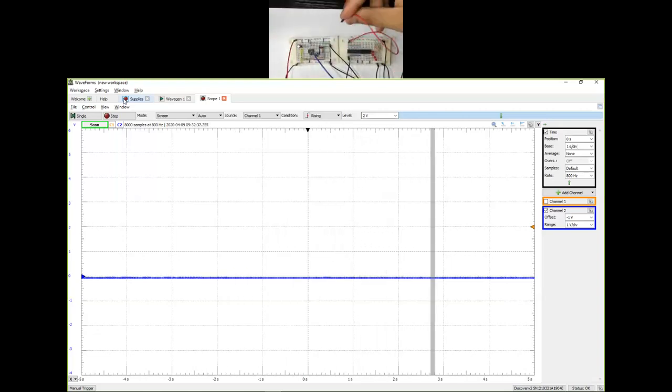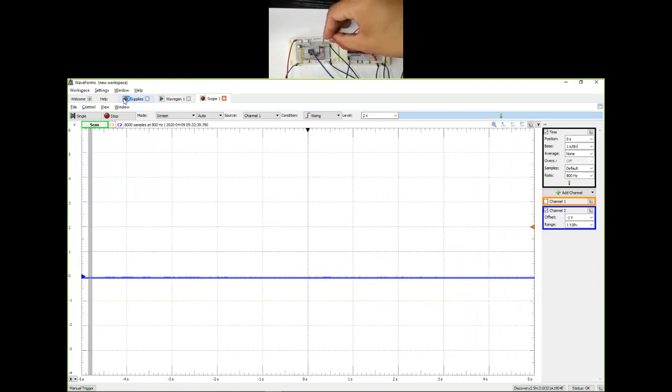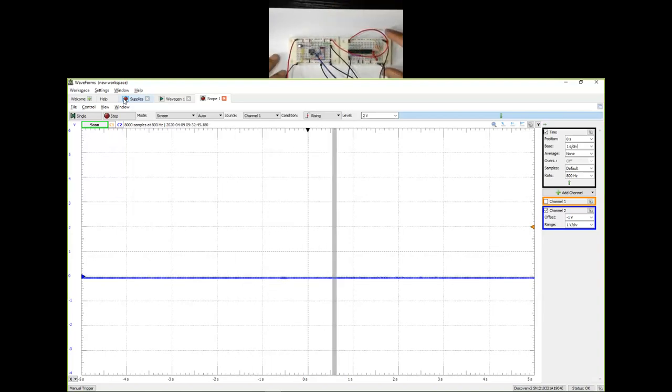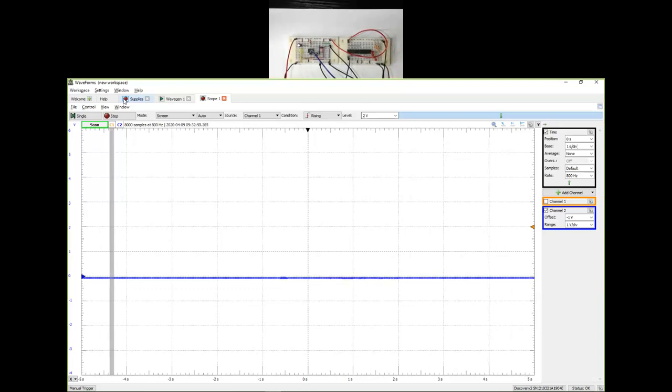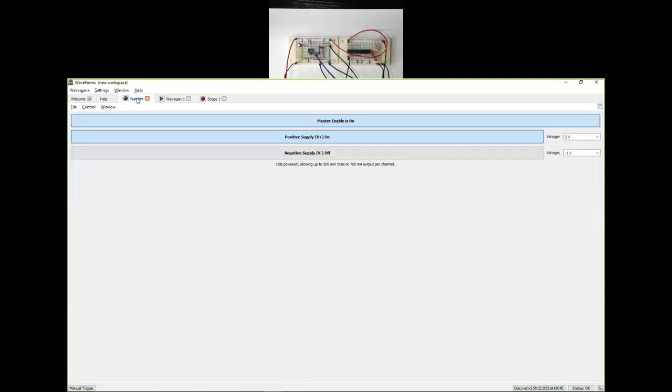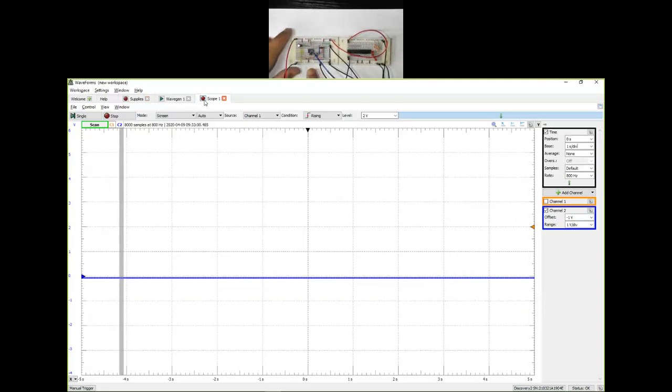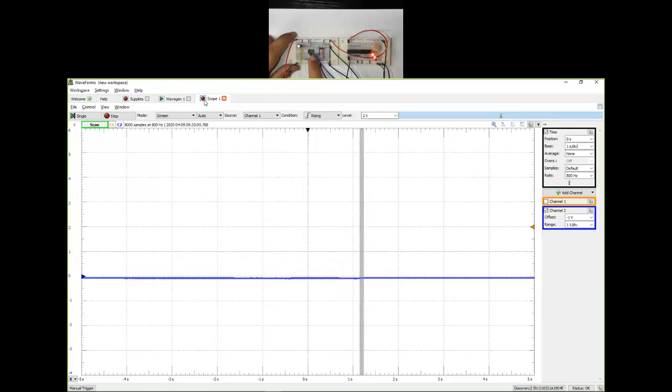Okay, so let me give it power and ground here. I'm going to give the power through this and ground through this. So I've connected power and ground to my counter board as well. Let's switch on the switch. Supplies are on. Let's see. So 0, 3, 4. Okay. So as you can see, I still have an issue here because it accidentally incremented by 1 a few times.